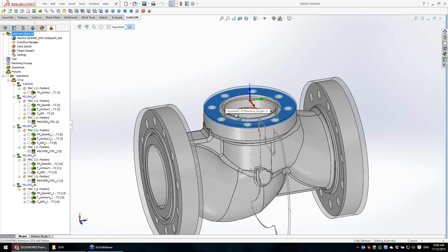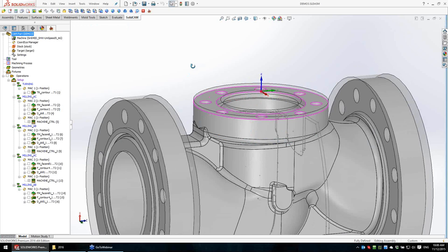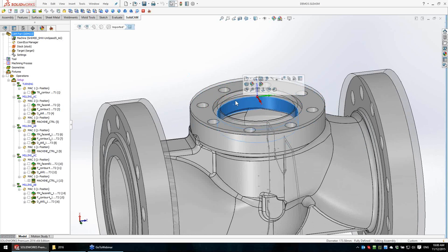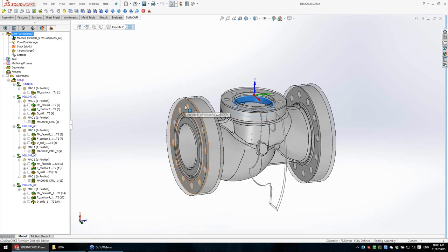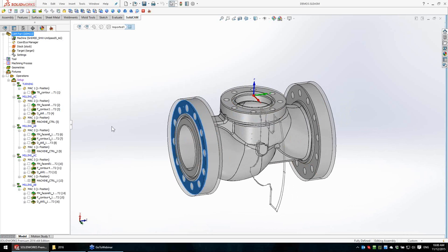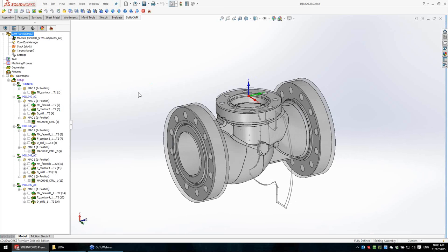So I will select the turning operation to remove the material from this face and inside the feature. And for this side and the opposite side, I will use milling and work with different sub-machines. Once I will work with AC and once I will work with AB. I will combine the operations with different sub-machines, and let's see how to handle it.